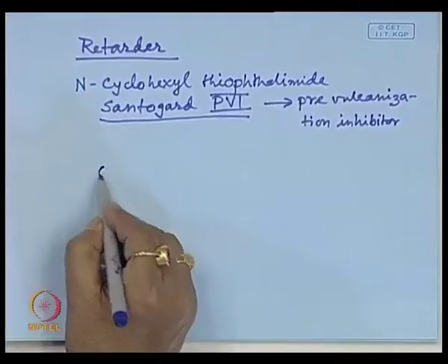Now, each such sphere can be considered as a nodule. Again, there is internodular fusion in a carbon black particle. That means one carbon black particle is not an isolated spherical particle. No, there is a fused nodular structure, fusion morphology. That means there may be many more such nodules fused one with the other.